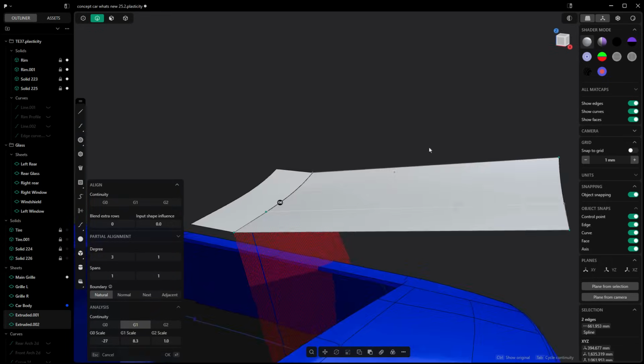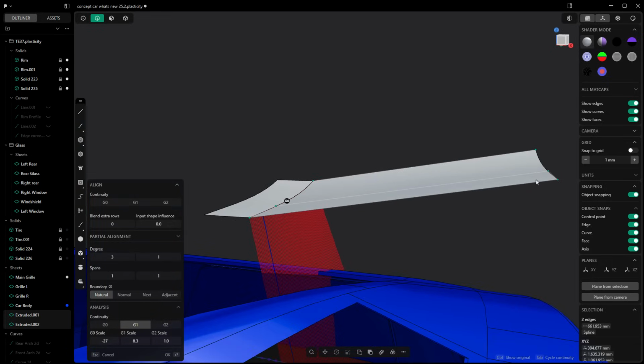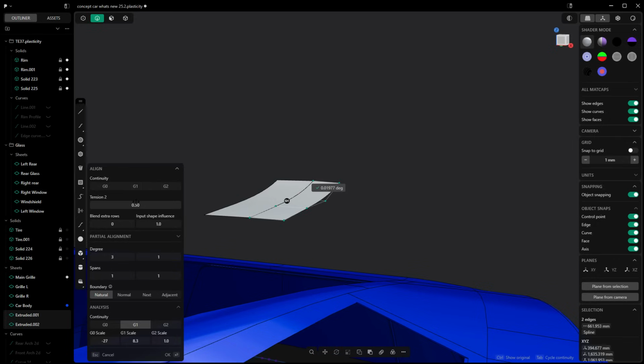You'll instantly note that the surface on the right-hand side has disappeared. Essentially, this command allows us to create a new surface that has curvature continuity, in this case G0 is the default, but G1 or G2 continuity, and allows it to gradually transition from one to the other. So it's keeping our second selection, and the first selection is beginning to go away.